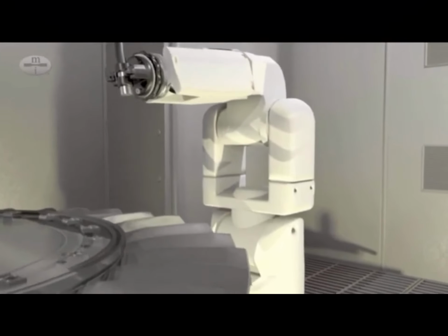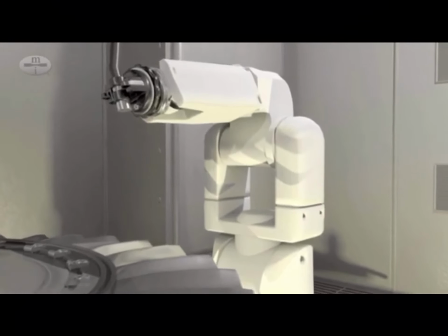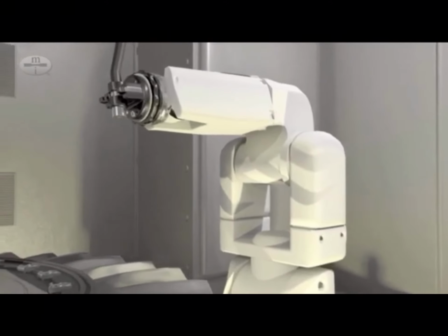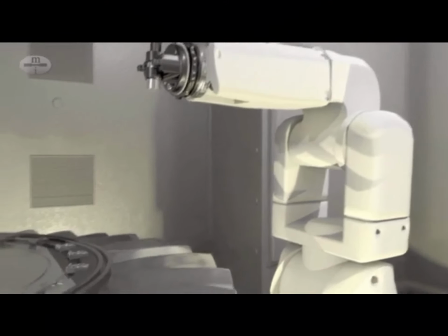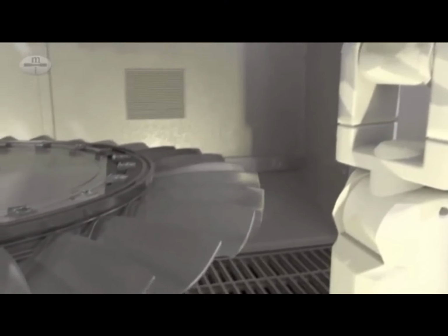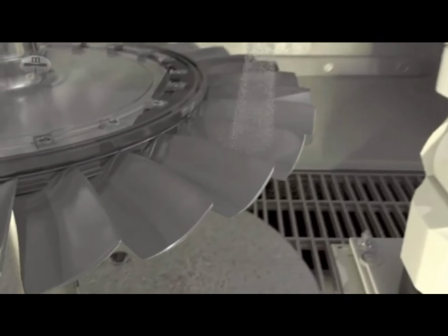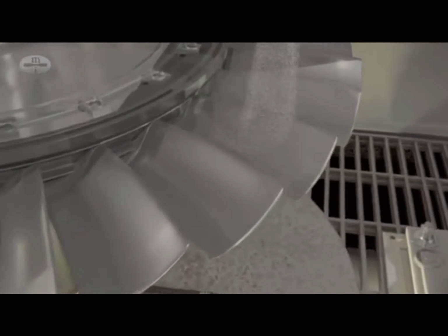The application of controlled shot peening improves performance, reduces maintenance, and provides a cost-effective solution to premature failure in critical components. Shot peening is a method of inducing residual compressive stress into the component by bombarding the surface with high-quality spherical media in a controlled operation. The media can be steel, ceramic, or glass, and each piece acts like a tiny peening hammer, producing a small indentation in the surface.